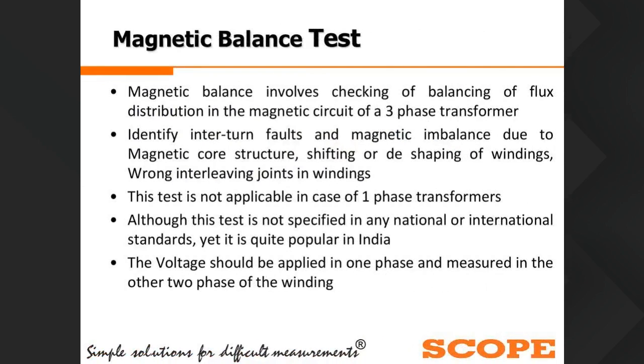Magnetic balance test. As I said, this test is not recommended by any IEC or IEEE standard, but it is commonly done by all the manufacturers to check the magnetic imbalance or magnetic balance of the core. This test is not applicable for single phase transformers. It is applicable for 3-phase transformers only.